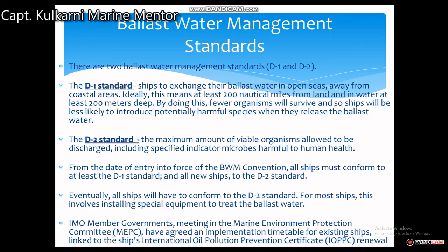D2 standard: the maximum amount of viable organisms allowed to be discharged, including specified indicator microbes harmful to human health. From the date of entry into force of the Ballast Water Management Convention, all ships must conform at least to the D1 standard and new ships to the D2 standard. Okay. In the D1 standard, we are carrying out exchange.